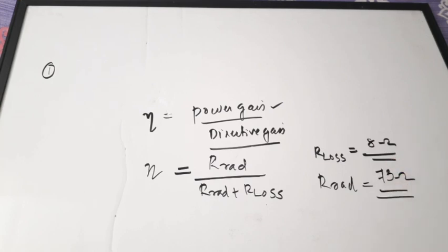While studying various types of antennas and their characteristics, you should study these things also, because in order to do the numerical questions, sometimes you have to remember these constant values. So here the radiation resistance of a half wave dipole antenna is 73 ohm. You can substitute this and this in this equation and find eta. That is our aim.